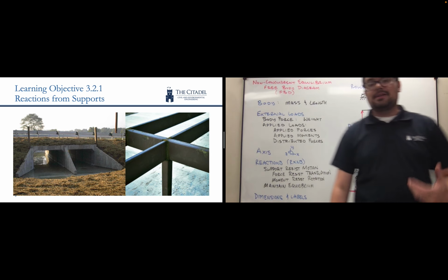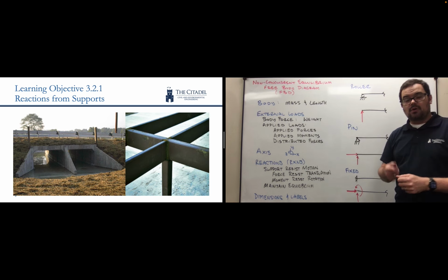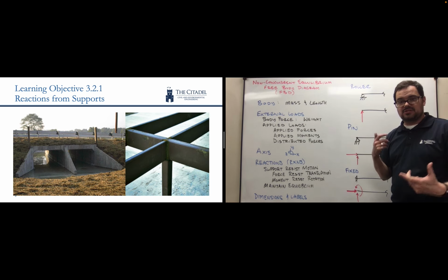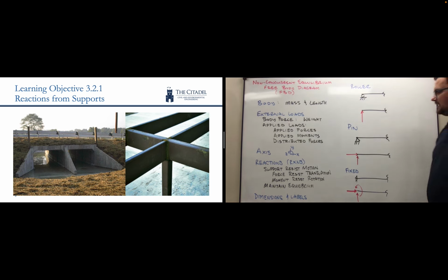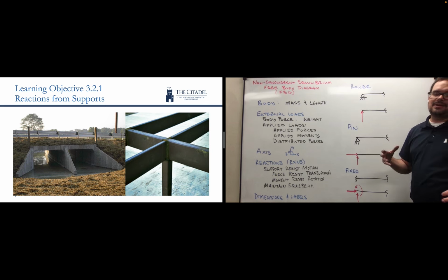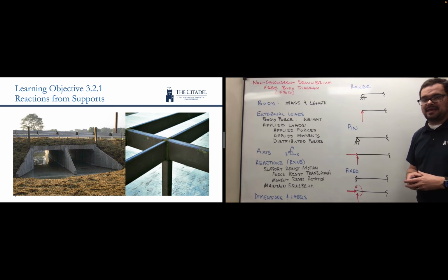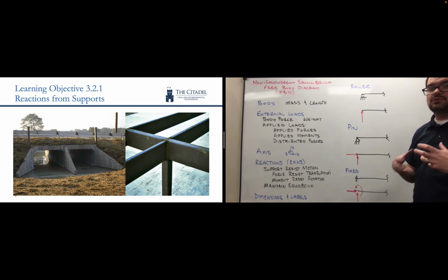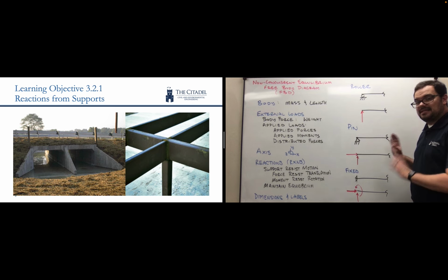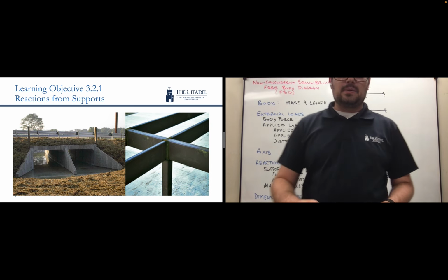We'll work a problem together where we use these things. We can also have a cable, which is a lot like a roller. It's pulling in the direction of the rope, just like we had in 2D particle equilibrium. And then your textbook has a whole table in chapter 5 that outlines all sorts of other different interesting connection types, most of which we don't use, at least in civil engineering. My mechanical engineers might have a reason to use one of these weirder connection types, but these are our dominant ones in civil engineering.